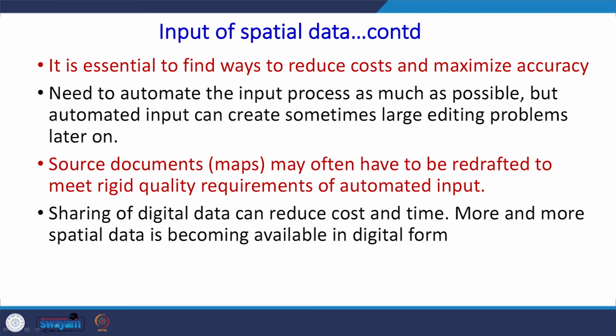But automated methods can sometimes be more time consuming because they require a very large quantity of editing. Like if you carry out a LiDAR survey, then you will have the entire data for every object which was present on the ground. So then editing is required in order to find the data which you don't require in your analysis and to delete that data.